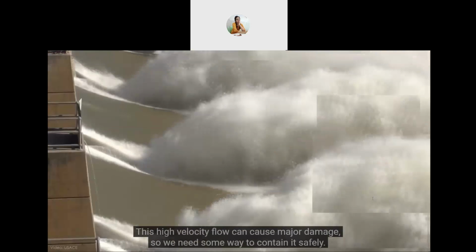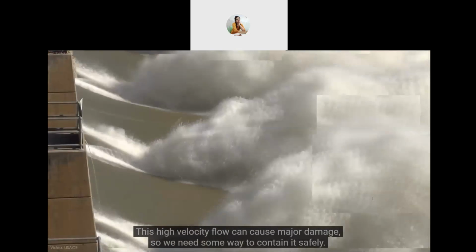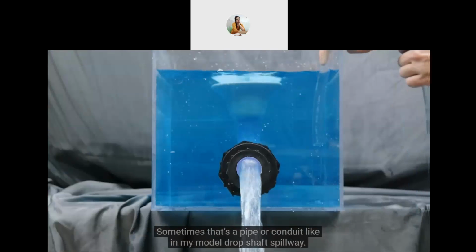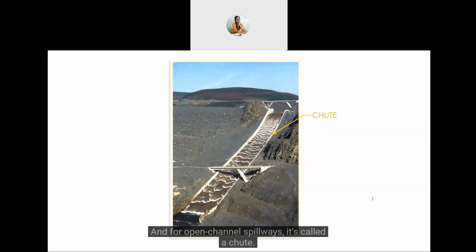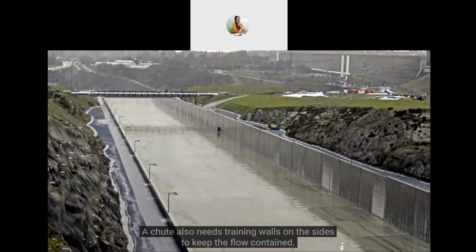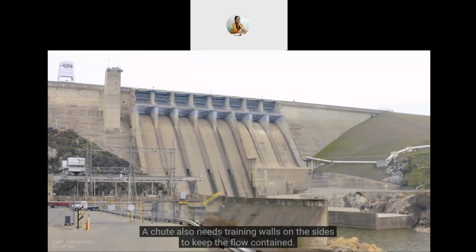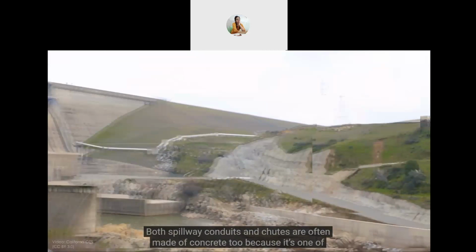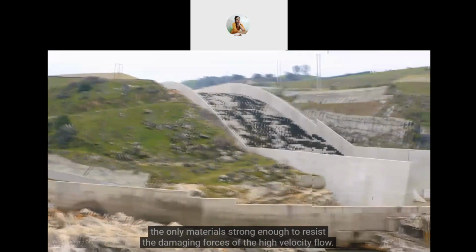This high-velocity flow can cause major damage, so we need some way to contain it safely. Sometimes it's a pipe or a conduit, like in my model drop shaft spillway, and for open channel spillways, it's called a chute. A chute also needs training walls on the sides to keep the flow contained. Both spillway conduits and chutes are often made of concrete because it's one of the only materials strong enough to resist the damaging forces of the high-velocity flow.